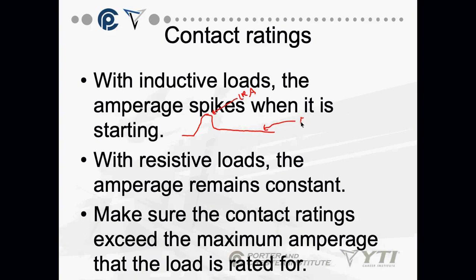So this is labeled either FLA or RLA, and that's for full load amps or run load amps. LRA is locked rotor amps.